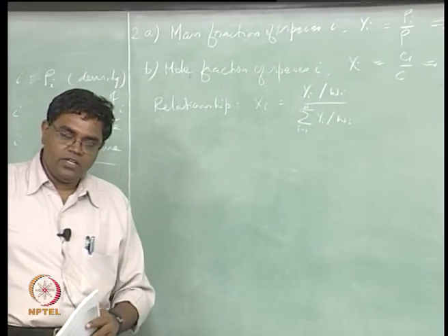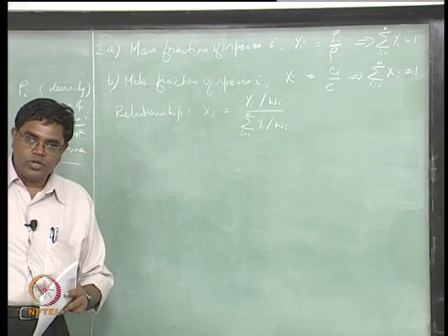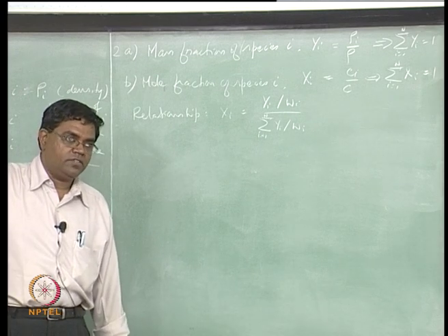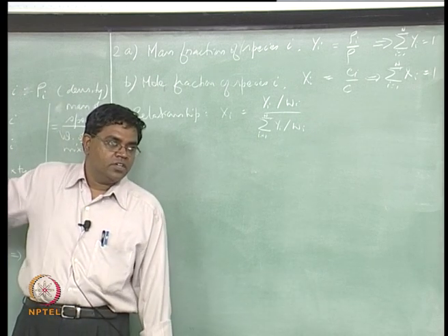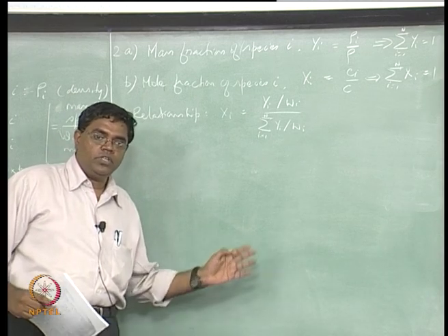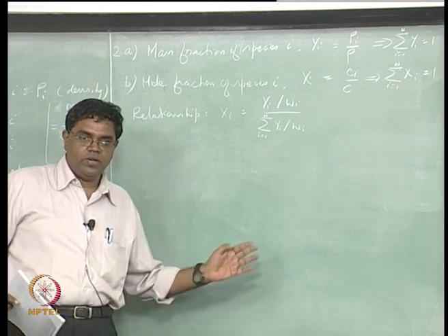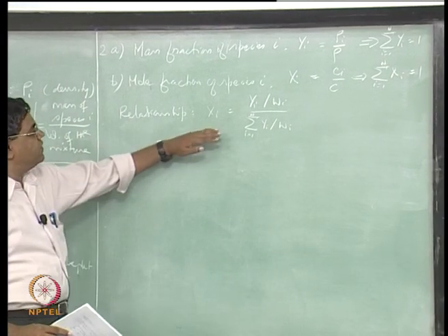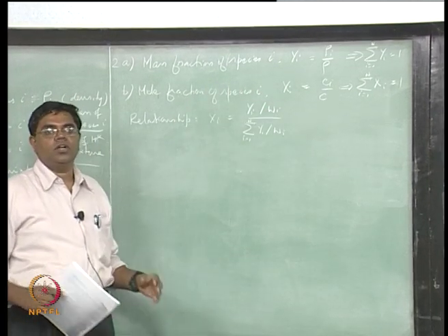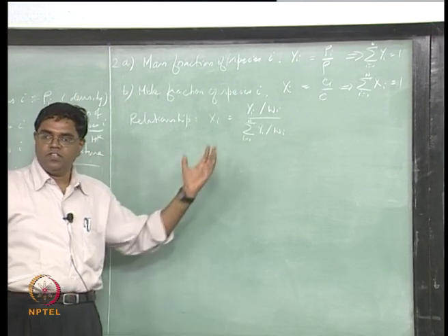So on the one hand, for the fluid dynamic equations, the conservation equations of mass, momentum, energy, we will be dealing with a mass basis, whereas for the chemistry and so on, we will be dealing with the molar basis, and there this set of equations relating the mole fractions to the mass fractions is going to come in handy. Okay, we need to have these set of equations.